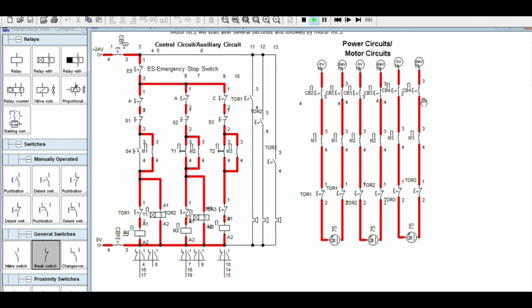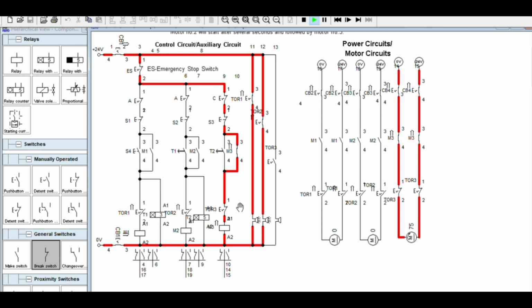But we are going to change the operation by modifying it. Say, turn off, then transfer on. So we will simulate the overload relay. Here, wait, here, then turn off the CB. We have the 3 alarms. Do not reset the overload relay, find the trouble of the motor, or turn off the main power.